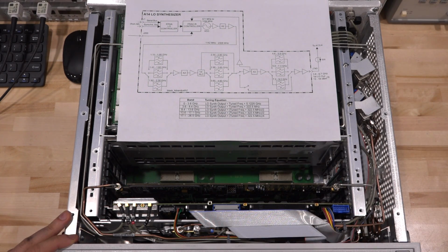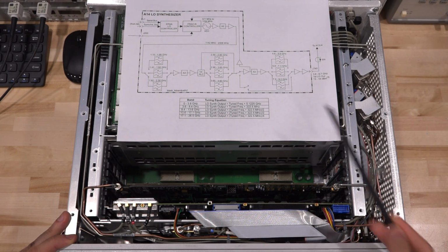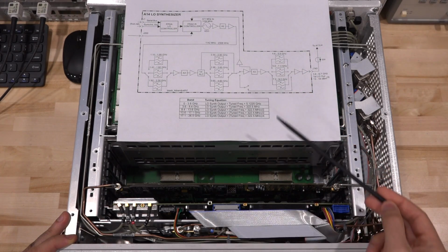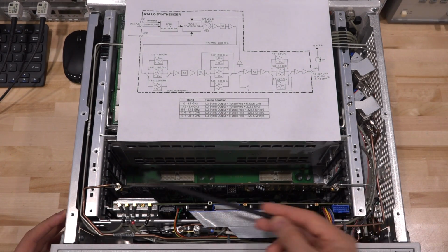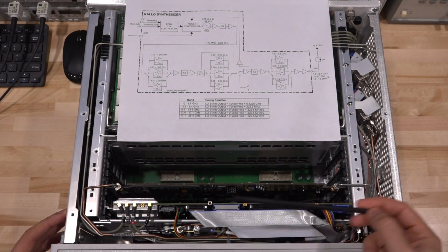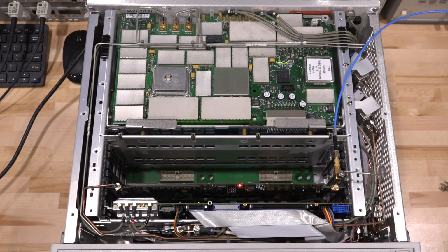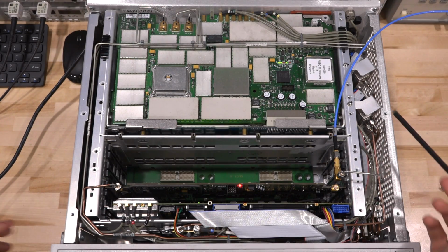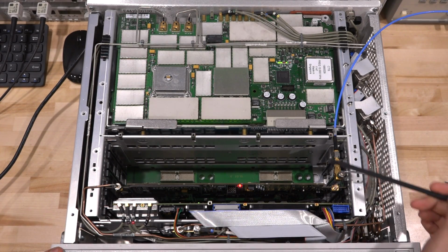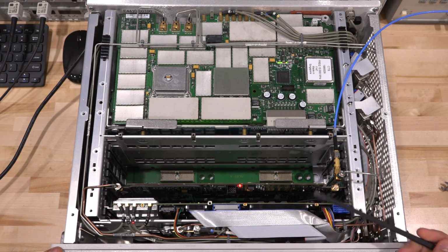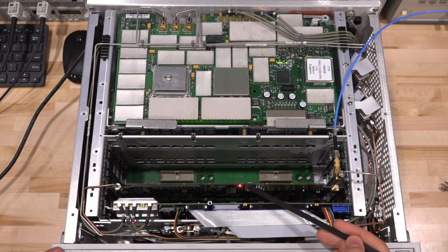So let's go ahead and turn it on. We can test this guy to make sure that the 4.8 gigahertz signal coming in here is nice and stable with the correct amplitude, and then we can take a look at the output and see which one of these doesn't work. Okay, the instrument is booting up, and you can see that I have bypassed that connector. It's going to a cable, it's going to the MXA right above, and there are some LEDs over here, which I believe are the PLL lock and unlock LEDs.